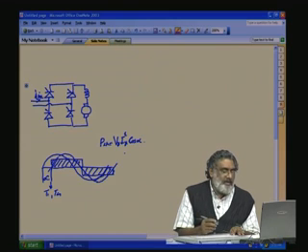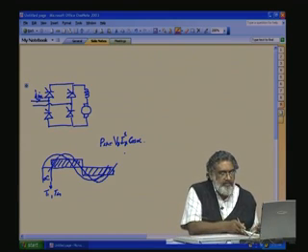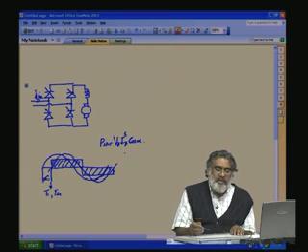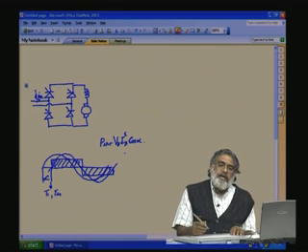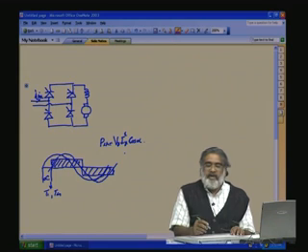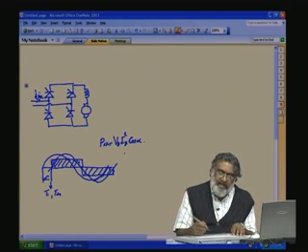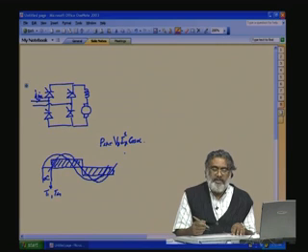And what is the problem with the power factor? We said that for the same power, as the firing angle increases, the input will draw a large current so that the power is constant. So, it can decrease the efficiency of the system, or with this higher current it can create losses in the system.